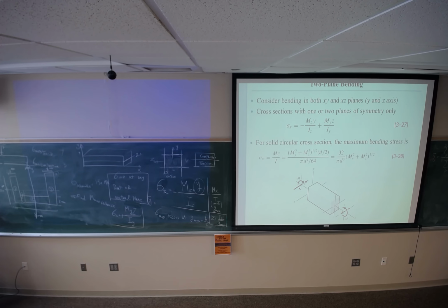For cross section 1, y bar is at the middle of this rectangle, which is 60. For the second cross section, if I ask you where the centroidal location is, it's going to be 8 divided by 2, which is 4 millimeter, and y bar 3, same as the first one, is going to be 60 millimeter. A1 is 8 times 120.